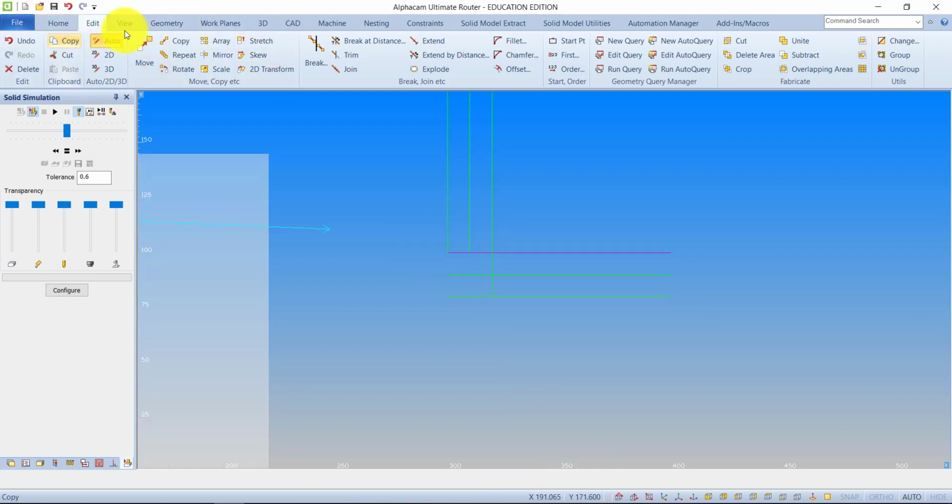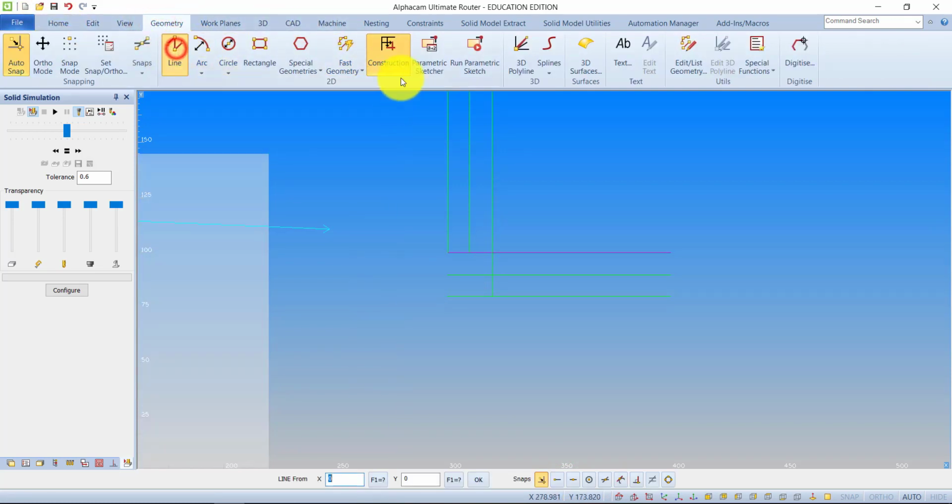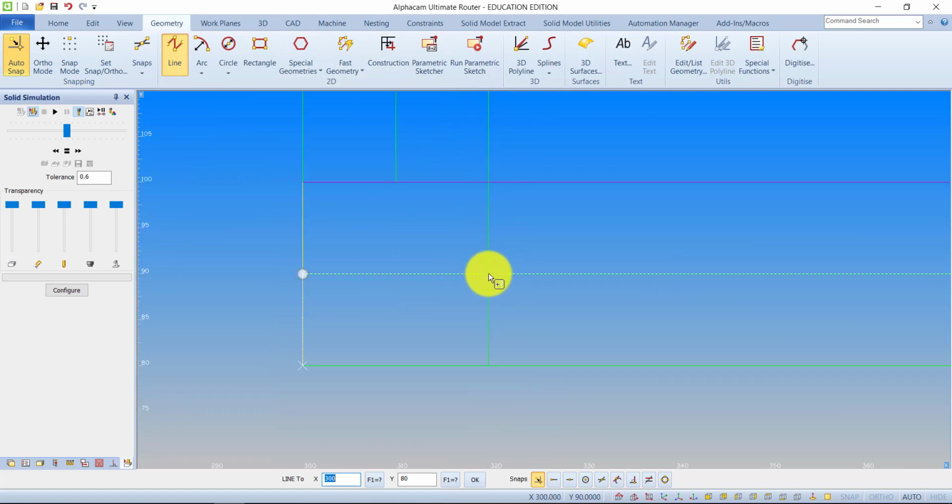So in any case, what you have to do is use geometry, not construction. Let's turn off construction. Use geometry to make a shape of a tool that suits you. So let's go to the corner there maybe. The reason I can't pick up that point there, by the way, I'm trying to snap on there, is because that's an intersection. So I need to get down here and press intersection and click the two lines, and now it picks up the intersection.